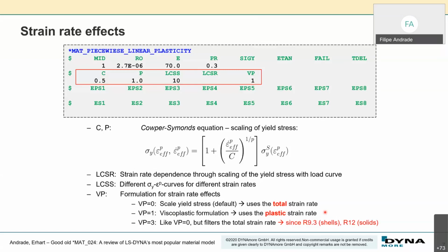Otherwise, it does not work. Those iterations are necessary to divide how much of the strain rate is plastic and how much is elastic. And in this regard, using the table, we have a very robust and very efficient algorithm that looks up the table, looking for the correct stress at the correct strain rate.